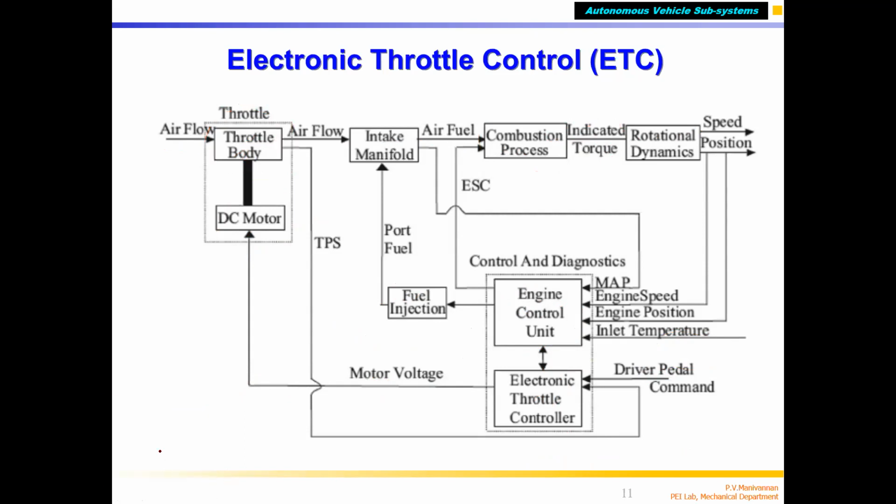So you can note down this functional block diagram. With electronic throttle control, the driver demands throttle by pressing the throttle pedal. The TPS sensor provides a voltage of 0 to 5 volts. You can remove this slight modification, this line, and only do it like this. The motor voltage is given by the ECU. When the driver presses, the ECU takes the TPS sensor value. You can see here, this is the TPS, which in turn generates the control.